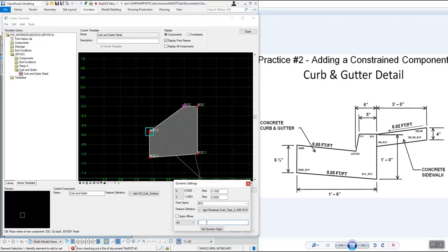Okay, so to do that, we're going to add in that slope. So we got HS again. We're going to go over 1 foot, comma, and then I noticed that negative went up last time, or positive went down last time, so negative. Let's see if it goes down going this direction. So we'll do a -5%. If we have to make these changes again, we'll come back and modify them. Okay, so that one did go down like we'd hoped it would. Okay, so we've got that one in there. Now, all we're going to do is right-click and finish.